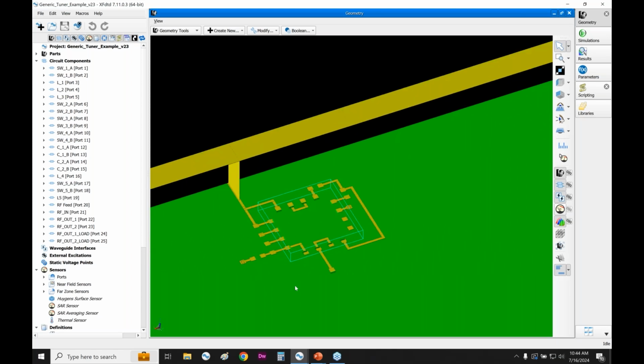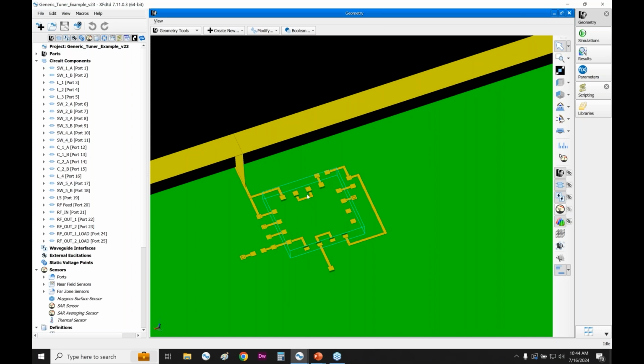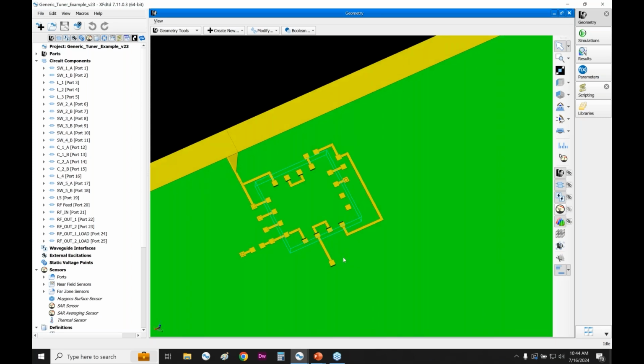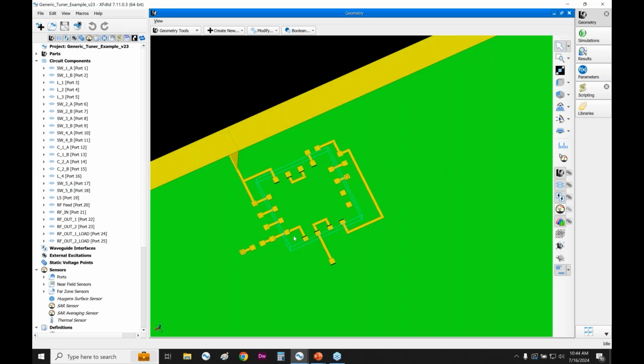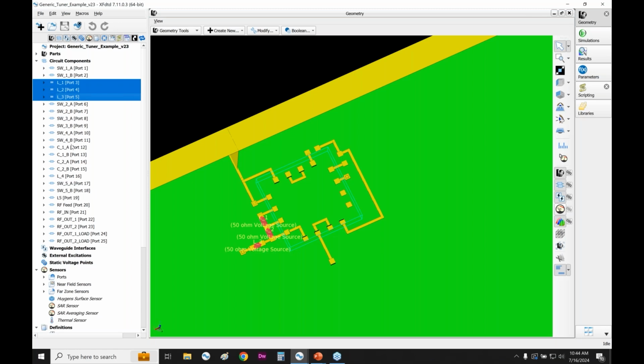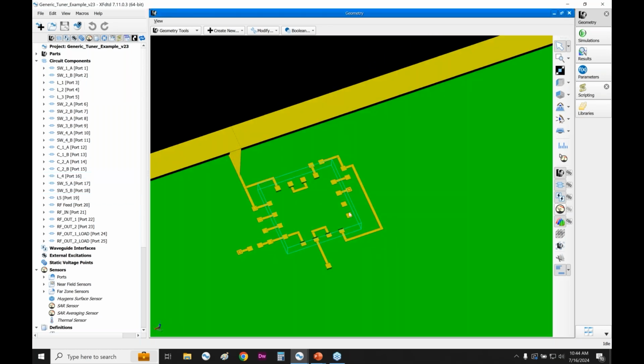On the input side of things, we have a much larger impedance tuner. Again, this is just represented in blue, so you can see which terminals are inside the impedance tuner and then which ones are outside. There are multiple ports here that are outside the impedance tuner that are allowing us to switch different values in and out. The impedance tuner itself has 5 switches within it, as well as 2 capacitor banks. And so in total, there's 25 ports here within the full wave simulation.